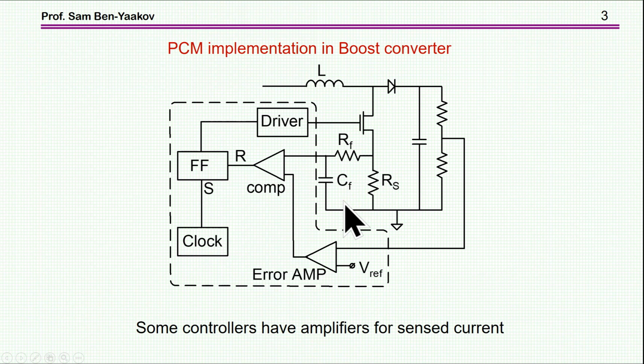This is in order to damp or filter out this peak arising from the injection of a current while there is a rise in the gate voltage. There is a current coming here through the gate to source capacitor, so there is a spike here. In order for it not to interfere, usually there is a filter here to suppress it.